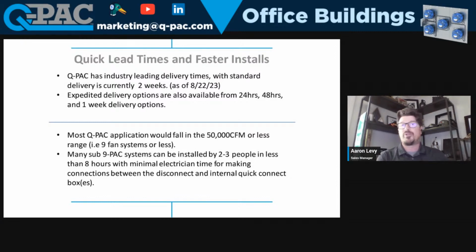Very minimal work from the electrician side. They normally come in and make their landing points, in most cases over a weekend. So BMS may not be available to come in and land their stuff until an actual business day. But the electrician can come in and make his line voltage connections to everything. And once the fans have line voltage, you should be able to run the system in hand mode to at least get air going until BMS comes and lands their points.